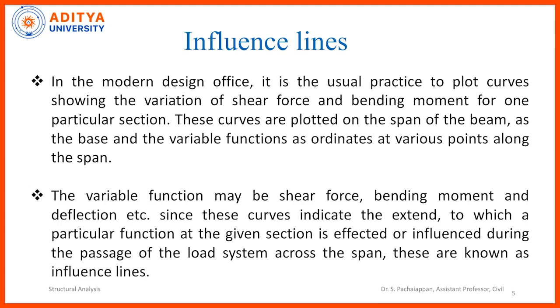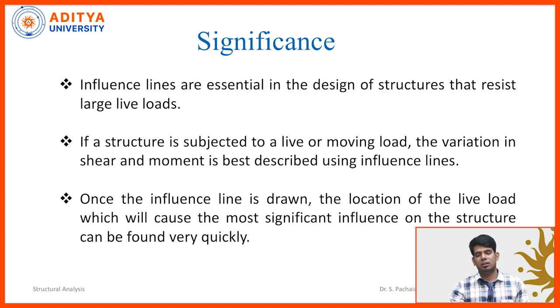Since these curves indicate the extent to which a particular function at a given section is affected or influenced during the passage of a load system crossing the span, they are known as influence lines. In simple terms, when a moving load passes on a bridge, the response of the bridge deck at a particular location is called the influence line diagram. The response may be the deflection, the shear force or the bending moment as well. Why it is important, we'll see.